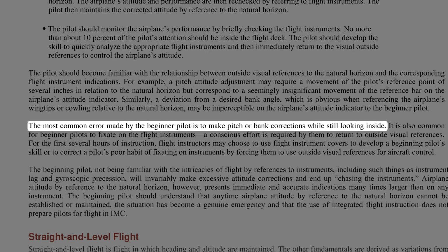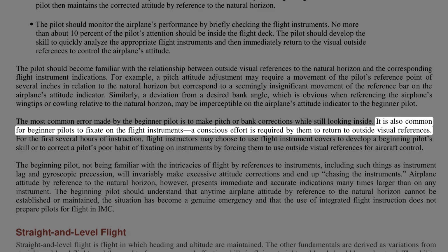The most common error made by the beginner pilot is to make pitch or bank corrections while still looking inside. It is also common for beginner pilots to fixate on the flight instruments. A conscious effort is required by them to return to outside visual references.